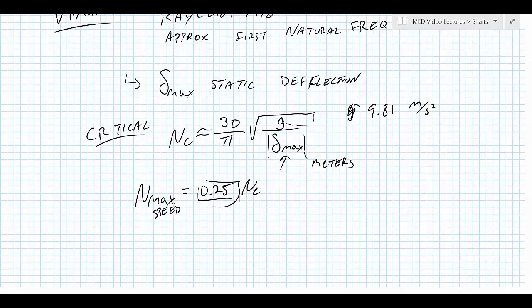All right, so what we've covered in shafts is basically the three main concerns. Is it going to fail due to static load or fatigue failure, crack growth over time? To take care of that, we look at having the right material with the right strength properties, reducing stress concentrations in the layout, which reduces bending moments, keeping it as small an envelope as possible, and then finding a diameter that will satisfy those constraints to keep it from either yielding or growing cracks over time, which is fatigue failure.